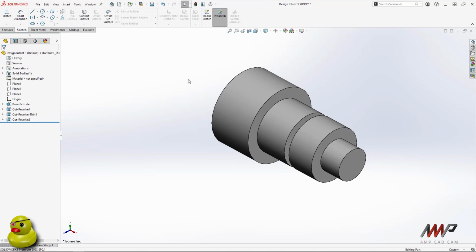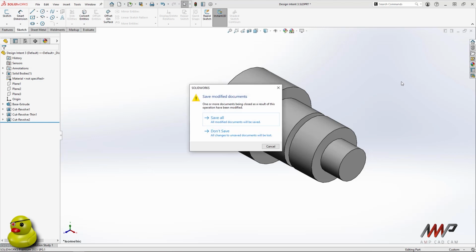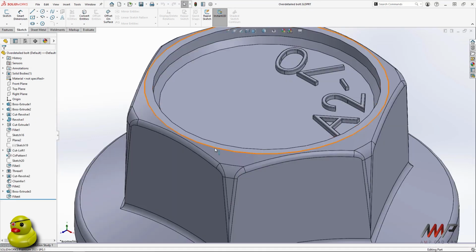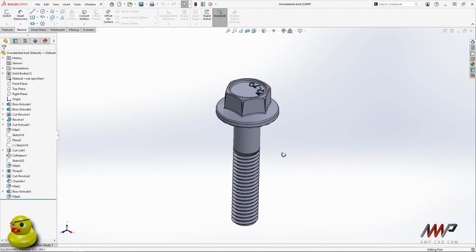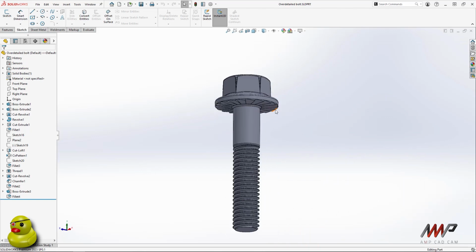The last thing I want us to shortly discuss before we start looking at the SolidWorks user interface is the placing of excessive detail on standard components. Although SolidWorks has the tools required to create extreme detail, these features should not be used for modeling standard off-the-shelf components. This is especially true for assemblies and will most definitely negatively impact your hardware performance.